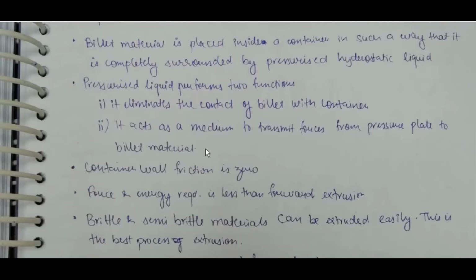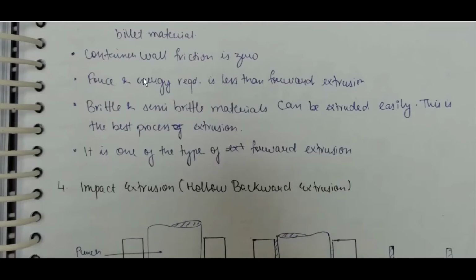If external load is not given, k equal to extrusion constant is not given, eta is given, then external load is equal to sigma y into A0, final extrusion load is equal to sigma y into A0 by eta.